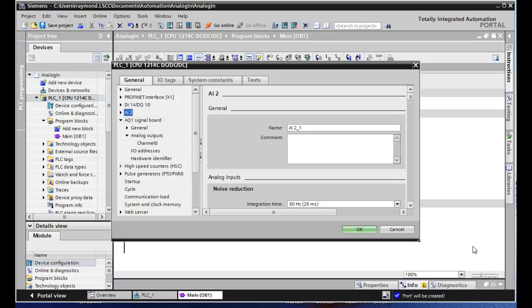It's going to fluctuate. Now you can use a 24 volt supply, but you've limited the range. A lot of your analog sensors will power up on 24 volts, but they only give you from 0 to 10 volts when they output, right? Does that make sense?